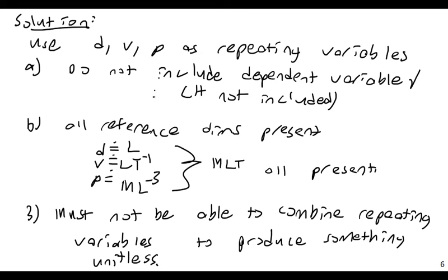All right, so if we look at this here, there's no way I can do that. The time only appears in one variable, the mass only appears in one variable, there's no way I can jumble these together by multiplying them, dividing them, taking them to some power, that these alone will give me a unitless term. There's just no way I can do that, and that's exactly what I want, a dimensionless or a unitless term.